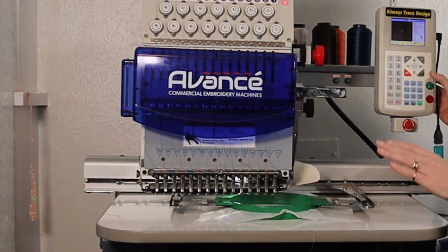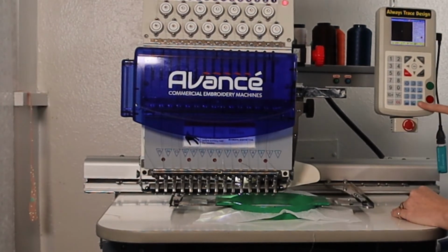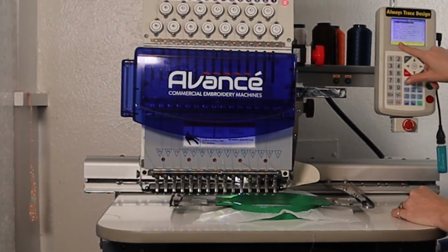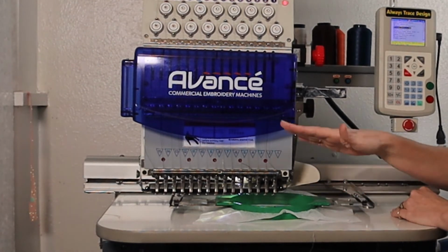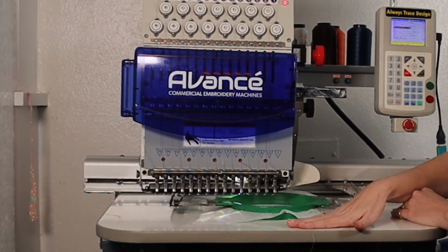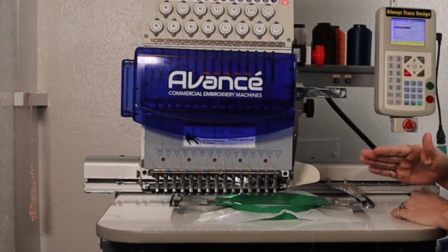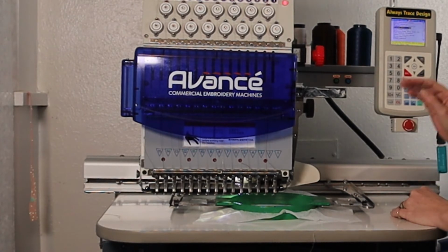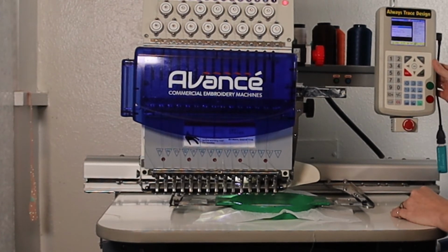Enter. Now, in order to do an offset, you hit the green button on your panel and select offset position set. What this will do is wherever you set your pantograph to come to, then every time there's a stop, it will move out to that spot. You hit go again, it moves back to where it should be. So we're going to select the number 4 option, offset position set. We're going to hit enter, and it says to move to offset, press enter key.